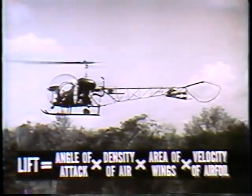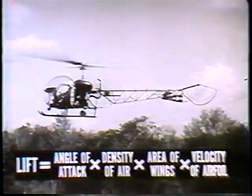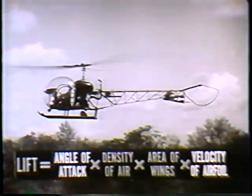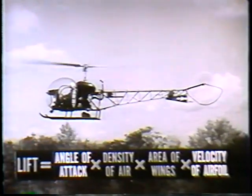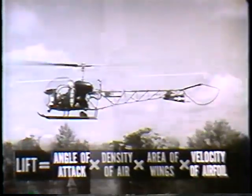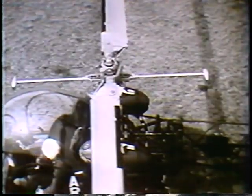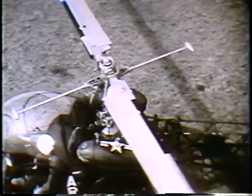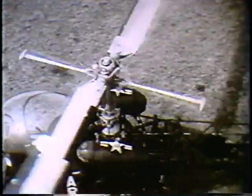Of the four factors which give you lift, the pilot can control only two: angle of attack and velocity of the airfoil. In a helicopter, the velocity of the airfoil results basically from the rotation of the rotor blades. A rotor blade is a wing or airfoil which flies in a circle, thus the term rotary wing.